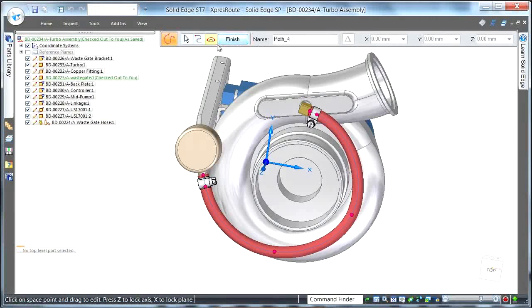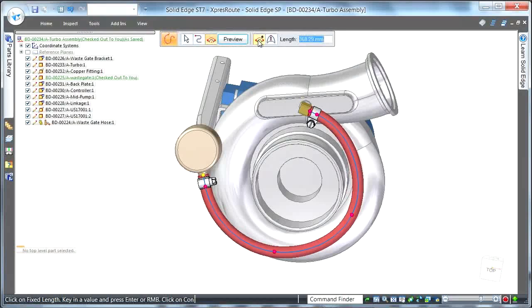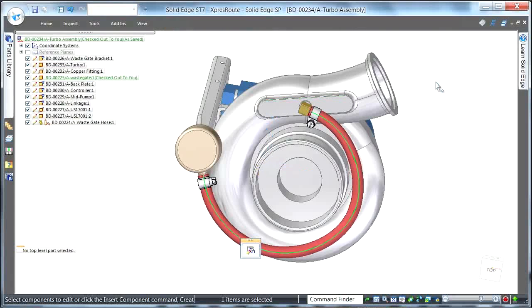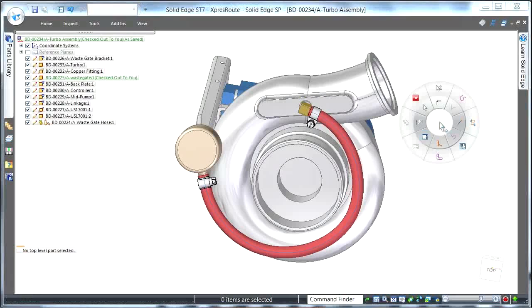When you're creating that curve, you have an extra option now to fix that curve length. So we can specify that as a standard length, off the shelf at 370 millimeters. You can also help it with this little triad, just help Solid Edge, so when you are adjusting that curve, you can prescribe which way it's likely to modify. So you've got control over this.